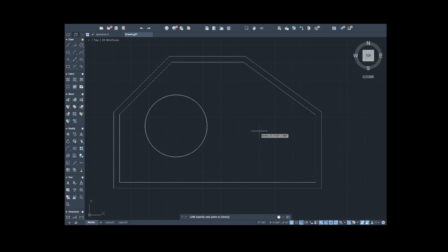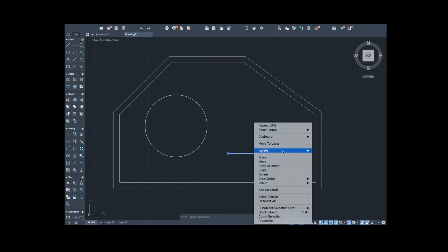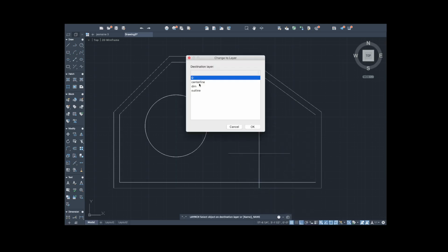And it's gonna go up 2 feet. So 2 feet. Enter. Right there. So I'm gonna draw a line there. Press escape, click on the line. The next, I'm gonna stretch this line across. I'm gonna click on this line, stretch it upwards. I'm gonna select these lines as my center lines. I'm gonna convert them. Right click, move to layer, center lines. Okay.